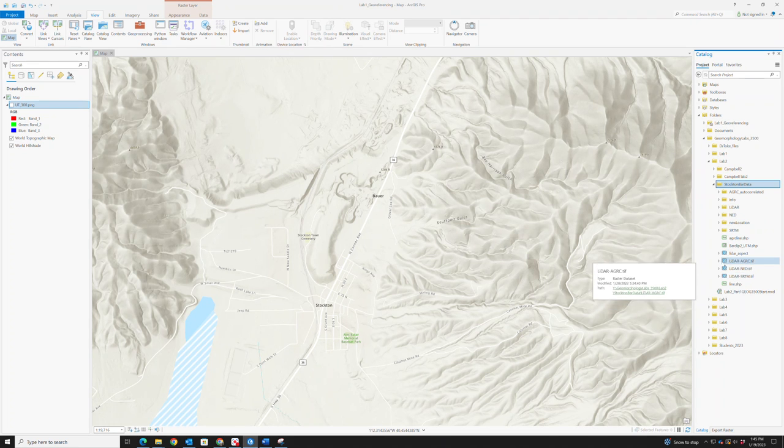So the .tiff files are DEMs, but in this case a lot of the work has been done for you. There are some subtraction files out here, and then within these folders there are the DEMs. For LiDAR data, high resolution, I believe 1 meter resolution.